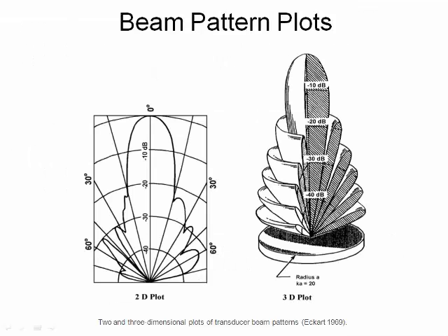And we've seen this before. Transducer beam doesn't really look like this in the water, but when we calibrate in the calibration barge, there's a test transducer and then a fixture that swings the test transducer across the reference transducer and measures the response of the transducer, and then this 3D representation of it. And that concept that transducers do have side lobes right at the axis of the transducer,